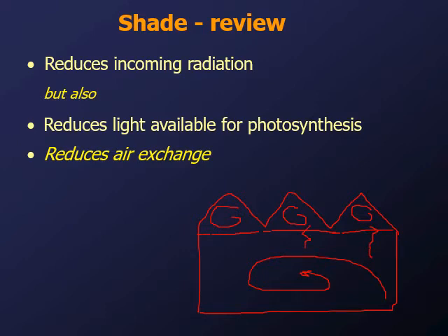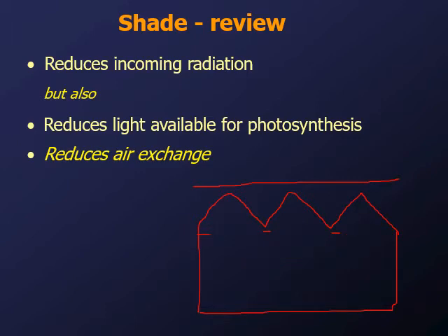That's why in tropical climates, the shade is often exterior to the greenhouse because then the heat isn't trapped in the gables. You don't have this situation. And it also permits heat then to escape the greenhouse if you have vents open underneath so that heat can escape the vents. So in really hot climates, this is fantastic. Now in our climate, in temperate climates where there's winter, snow and stuff like that, we can't do this because the snow load would land on this and it would tear it apart.